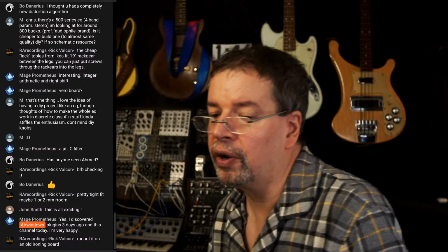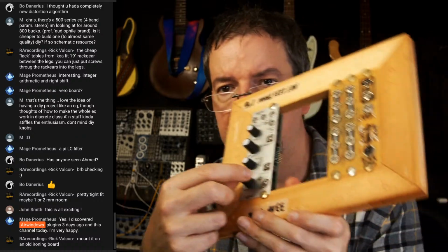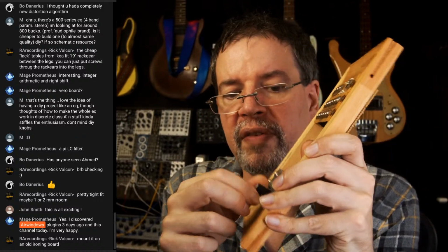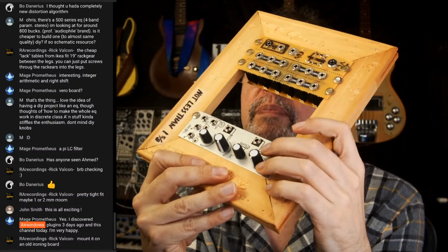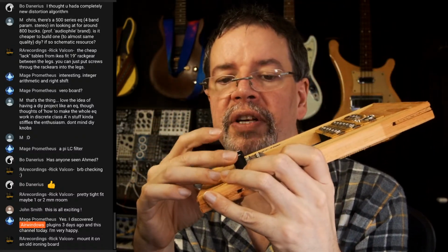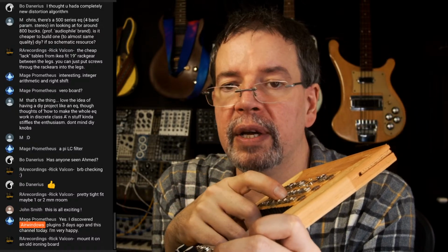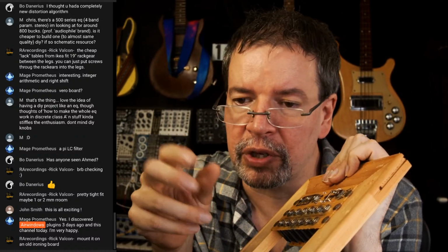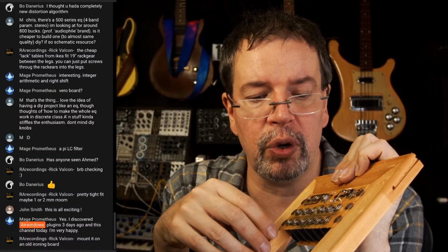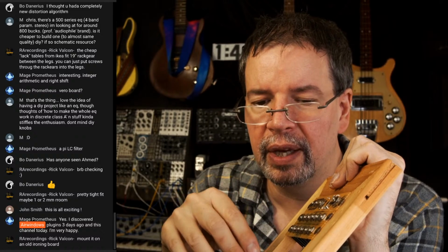For instance, I've got all of these trim pots. These are potentiometers, but the total of everything in these potentiometers costs a couple of bucks or more, depending upon how big they are, how fancy a knob you're using, and so on. Trim pots can be much cheaper, but they're tiny, and the bit that turns is tiny. You have to use a screwdriver. So you could either use a screwdriver or glue a piece of perf board on there so that it's a bigger thing that you can reach and turn, as long as there's space to do it.